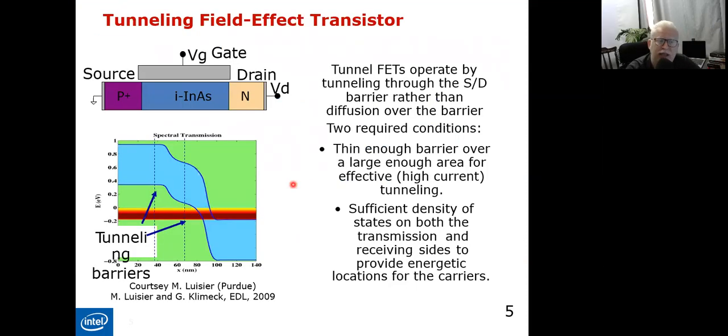So one of these technologies may be the tunneling field effect transistor, which we can think about as what we call a PIN structure. I'm not sure if you have heard about this junction before, which is a PIN, but following our background in this module, I think you can think about it in a very good manner. We already have studied together what's called the PN junction, which is the normal diode, and we have seen these PN junctions in more than one format. Herein, we introduce an intrinsic layer in between two doped layers. One is P, one is N. This is what's called a PIN.